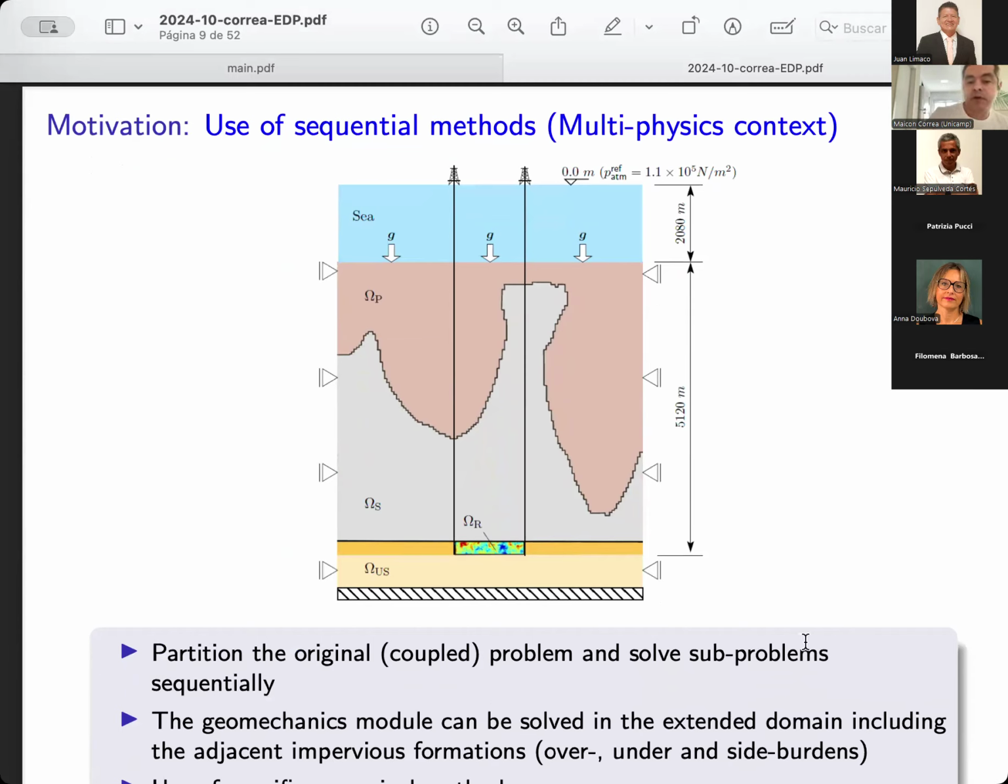So if it disappears, you lose track of this part that's really important. So the idea here is this illustration of that. We have the pressure dependent data, and this last one here shows how you increase the pressure, you are increasing the dissolution, the gas is dissolving in the oil till the point you don't have gas anymore, and this function becomes constant. So this point here is where the gas disappears. It's called the bubble point pressure. So this is the pressure where all the gas becomes dissolved.